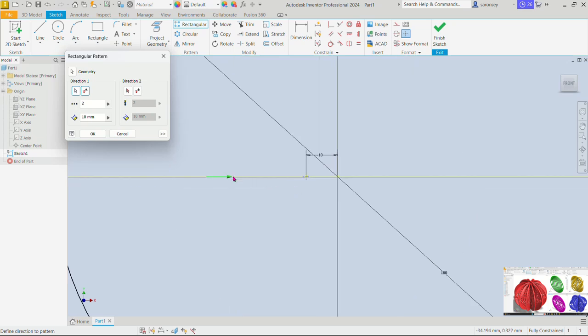But let's see the first preview. This is the first preview. It is moving away, but we want it to go this way. So what we have to do is to select this option that says flip. And now we can flip the direction of that point. We are also to specify the count, how many of those points we want. We want 4 of them.